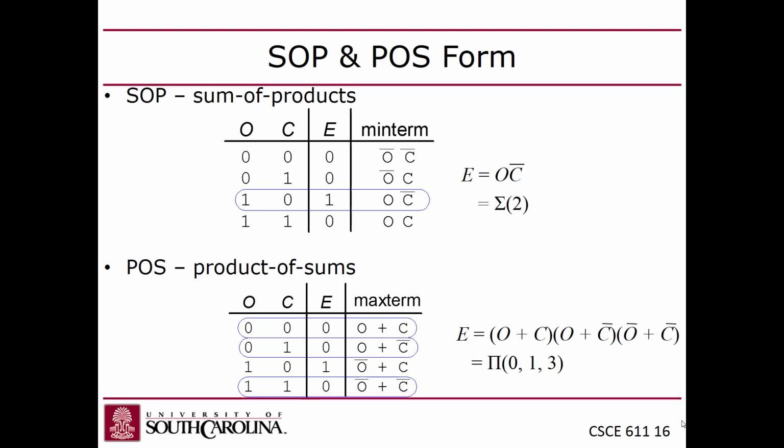Okay, what would be the advantage of one or the other, by the way? Why would I go one way versus the other? Well, these are equivalent. This Boolean expression and this Boolean expression are equivalent in the sense that they both give you the same truth tables, and they are both true under the same conditions. They're both false under the same conditions, right? So it's redundant. Why have two ways to do it? It's the same thing. Yeah, this is pretty rare. Most people don't use product of sums.